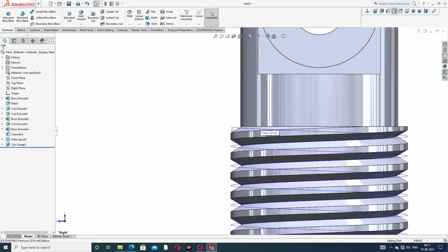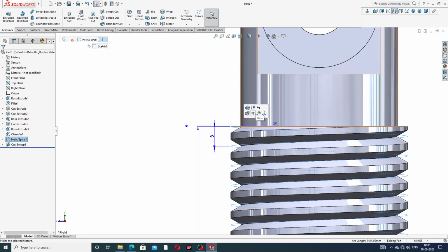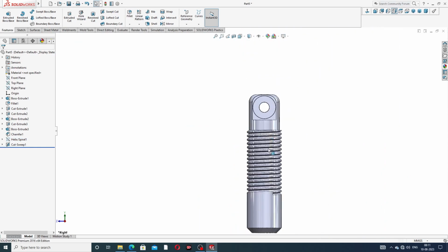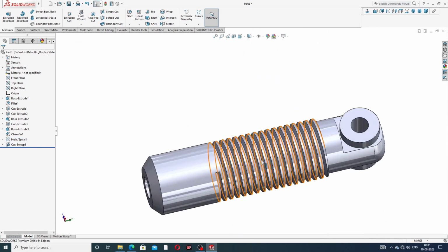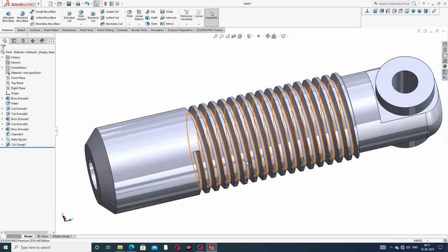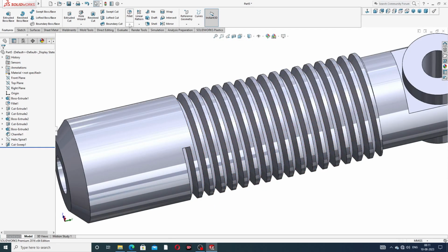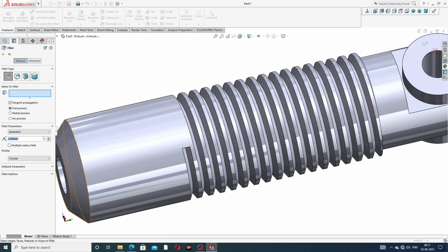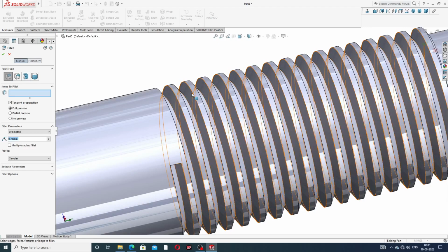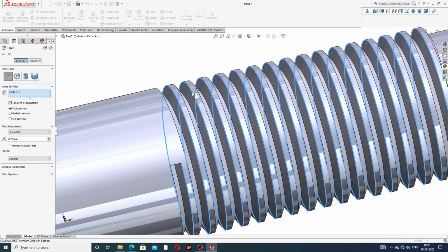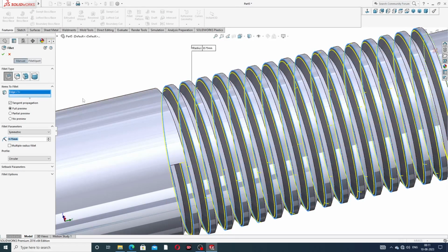this cutout is better, and this line is hidden because this is looking perfect. Okay, and some fillet is used here, and this fillet is 0.75 millimeter, which is perfect, and select this. Okay, all is perfect and all is correct, and click OK.